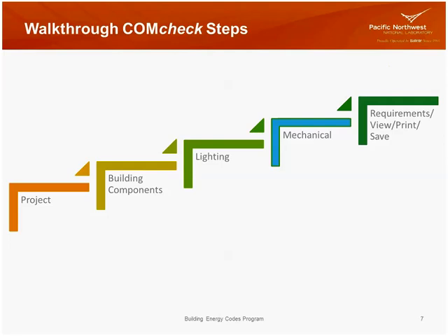Again, not all of these might be applicable. For sure, you would have to enter your project information, but maybe you're only doing building envelope and you have a lighting designer that's doing the lighting portion. That's fine. Maybe you share the file. The big plus about the COMcheck Web tool is that you can have other designers that are involved in a project enter their information for their systems and save one overall compliance report. So that feature makes it really nice to use the web tool, where you wouldn't have to send a data file, but you could compile the entire thing. But here's the basic walkthrough steps. So let's go through these.